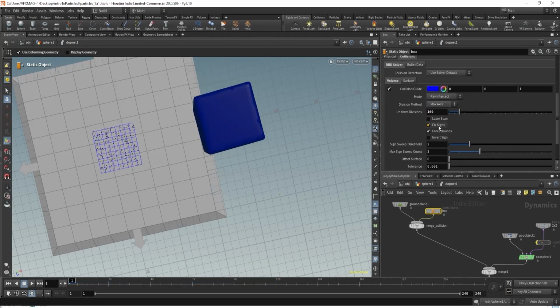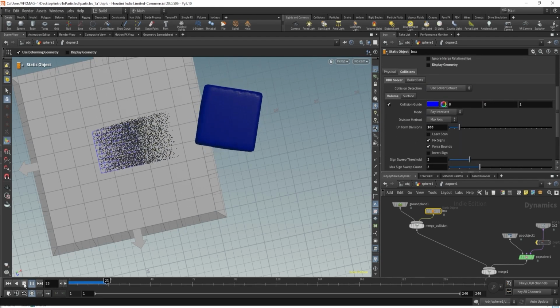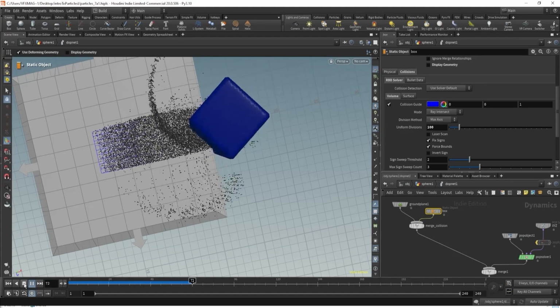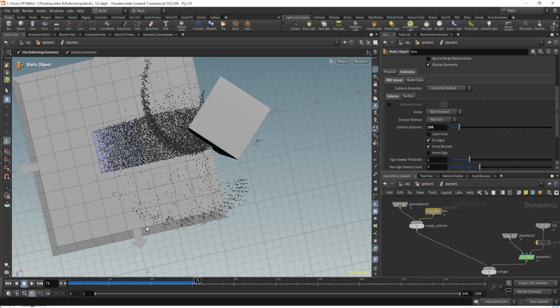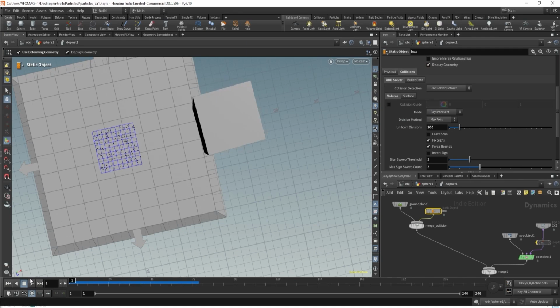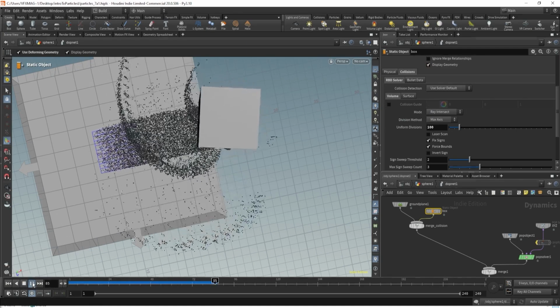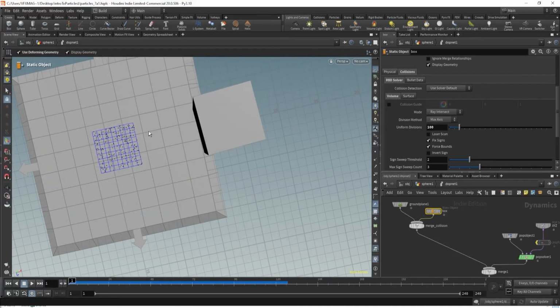And there are other options over here as well, but those are not useful. Just you can use these, but it will affect simulation time also. And if you keep this visualization on, it will take more time. If you turn this off and turn on this, then it will take lesser time. It's creating volume on every frame. That is also one reason it's creating those gaps. And in fact, we can fix that without substeps also.